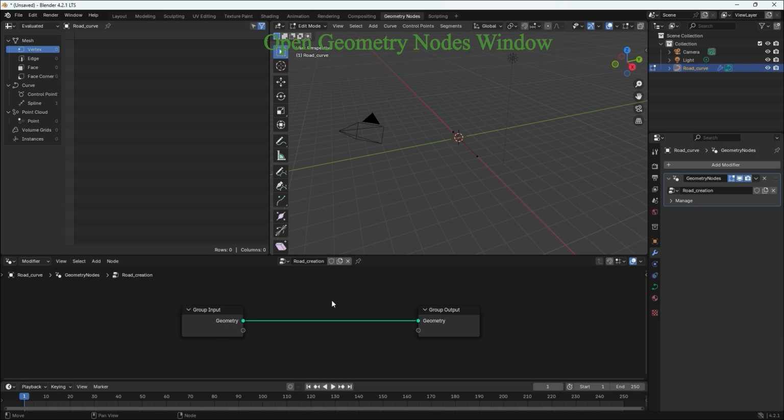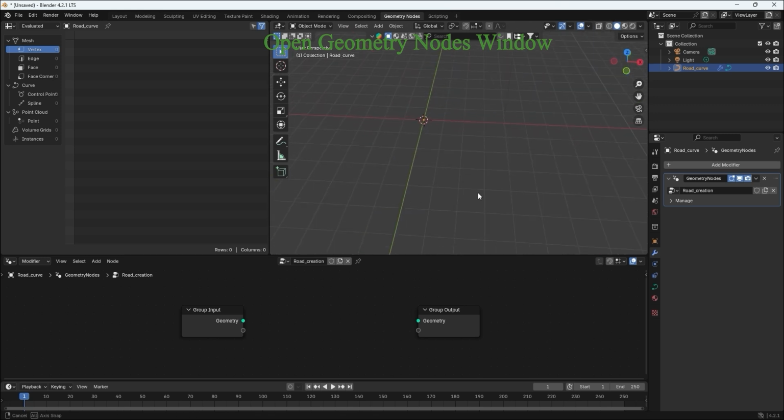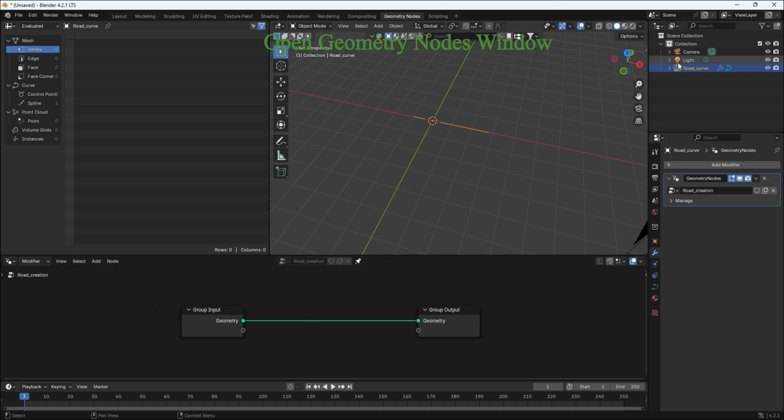And if I delete this line, that removes the Bezier line. So now we do not have anything. If I connect it, I can see that the line is up here now. So this is the main advantage of geometry nodes. We can manipulate things within this node tree. I'll pin it, so it is not going to disappear if I change another object. If you want to delete a connection, press Ctrl and use the right click. That will delete the connection.